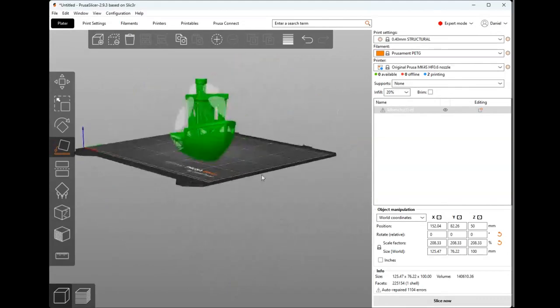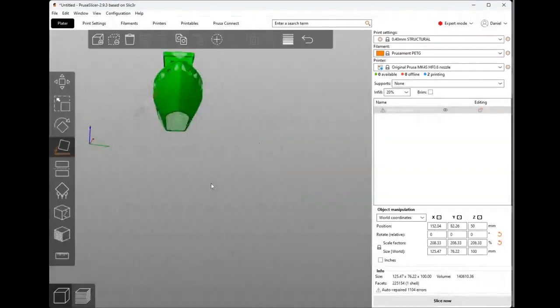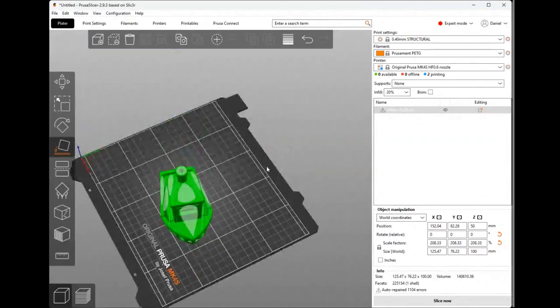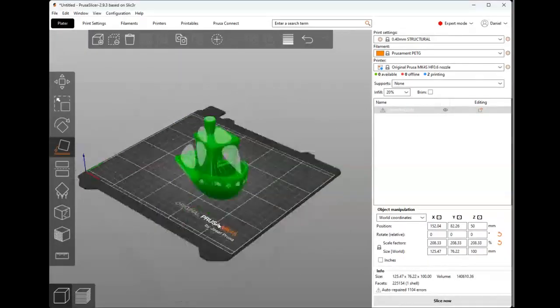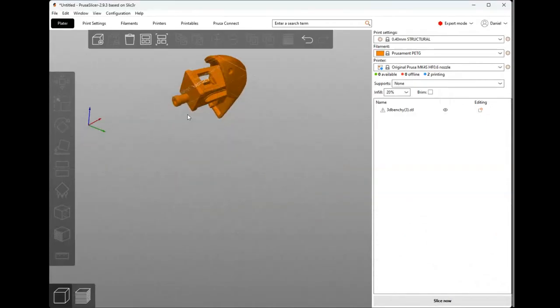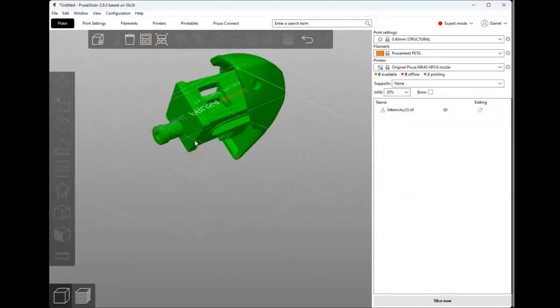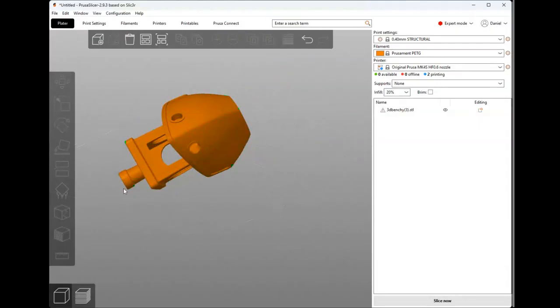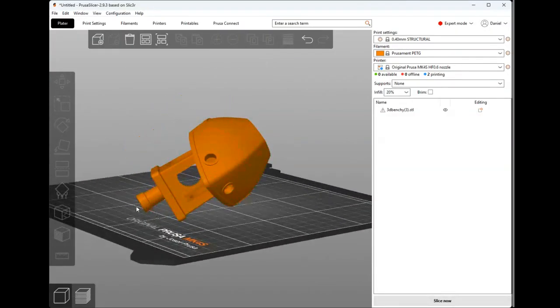So one of the things to note with 3D printing is that you want to have good contact with the base plate right here, the print bed. So if I place it like this, when we go to print it, you're going to get very, very poor contact with this line and this line. And this will be the base that all the weight and all of the printer movements are like lever on, you know?